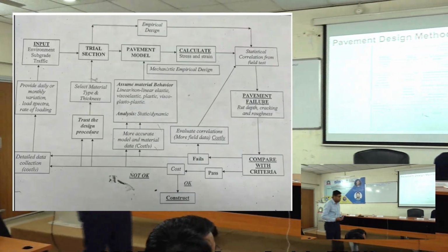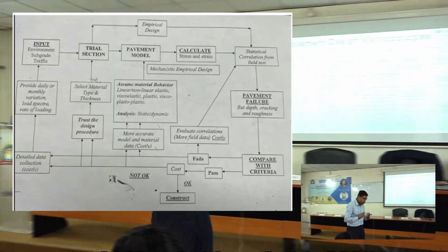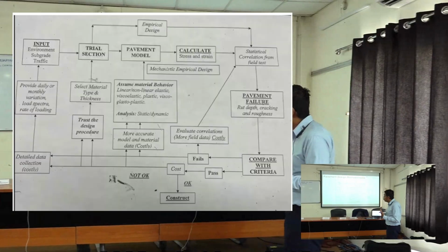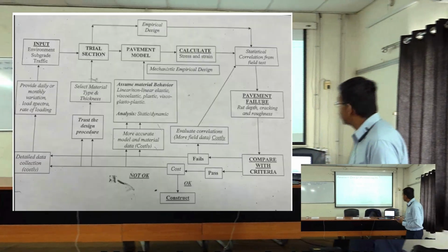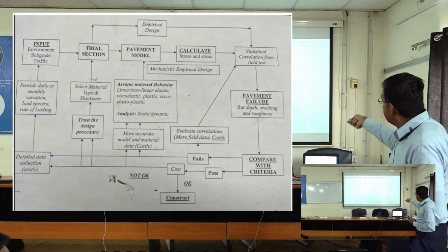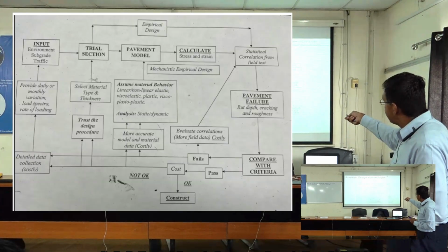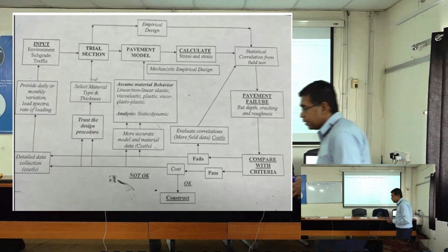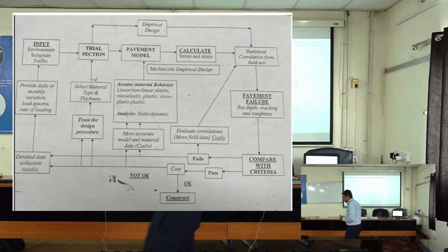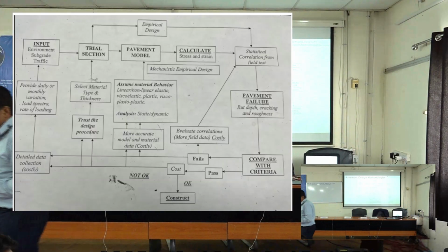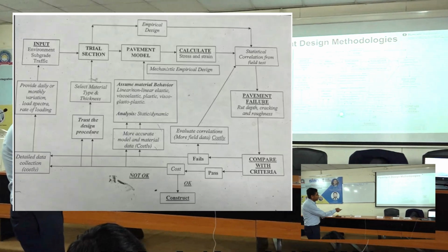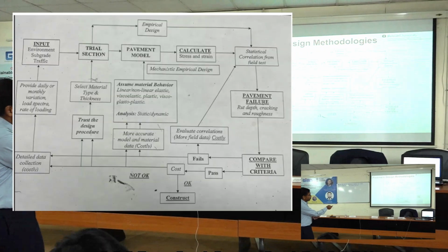As I told you earlier, with the New Jersey Department of Transportation, we recommend they do this kind of analysis every so often to increase the accuracy of the stresses and strains and the correlation with field data. That is how the mechanistic empirical pavement designs will get more robust and more accurate. Another way is, of course, spending more time on input parameters.